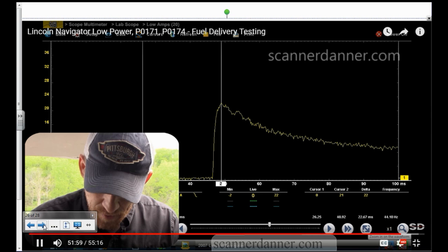This is the new pump. After I'm done, initial turn on, what do we see about the current flow? Same as the old one. How's my pump power and ground on this vehicle? It's good, right? This is all the procedures that we're going to be talking about in chapter 14, chapter 15, chapter 16, what we're covering now. All this stuff really plugged into one video.